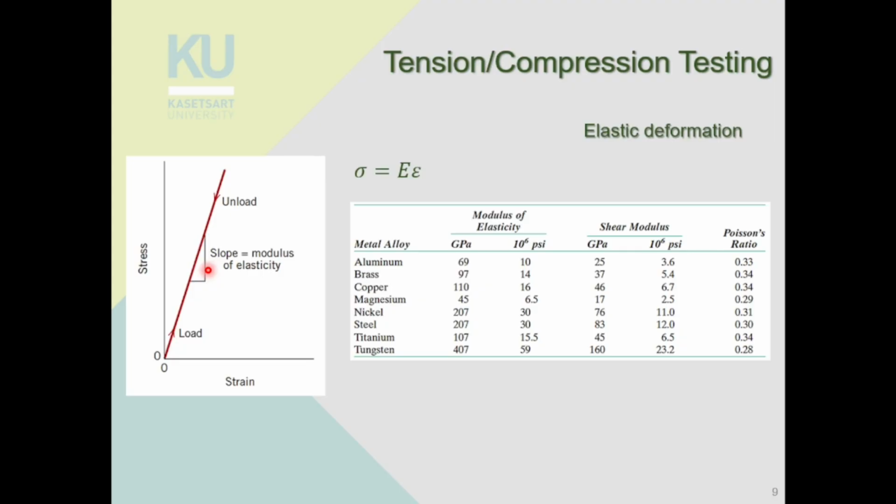So we have to choose a material with a high enough elastic modulus so that the wings don't bend too much during flight, or you will lose all the aerodynamics that the wings were designed for. The wings will just lift up a little bit, and when the plane lands, the wing will go down to the original position again. So you have to choose a material with a high enough elastic modulus so that the wing doesn't go up so high that you lose aerodynamics and lift, and the plane cannot fly anymore.